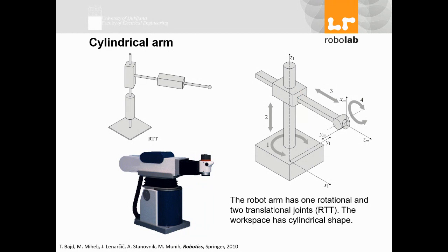Mike says SCARA is faster to pick and place. Mike, is it because of its design? You have pneumatic. You know that pneumatic actuators are normally, well, it's hard to say because we have electrical, but pneumatic mostly are good and fast. You know, light, and you don't have a motor to move. You just have air pressure.